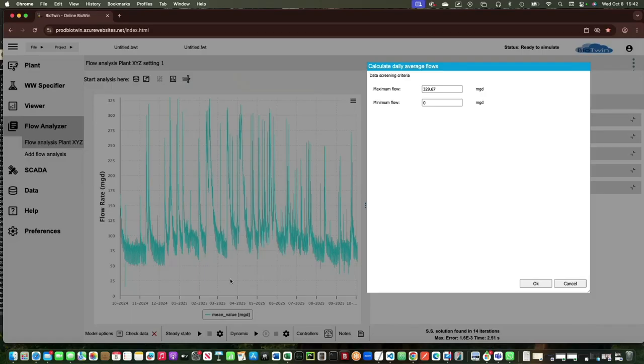Well, then all we do is we specify a minimum flow of, let's say, for example, this value of 25. You see we have one line going below 25. Let's pretend that that's an outlier. So let's say realistically we don't expect anything lower than, say, 30. Anything lower than 30, treat that as an outlier. And that means that I will simply enter 30 into this minimum flow box. And you can also do the same for maximum flow.